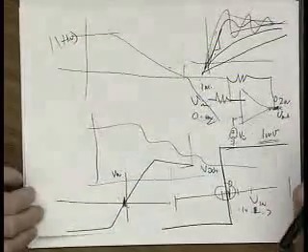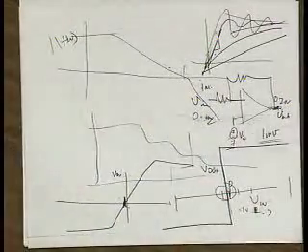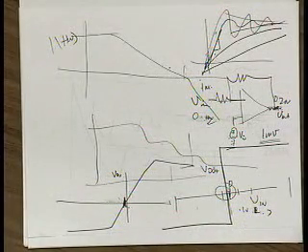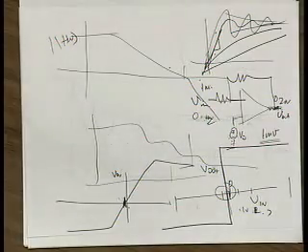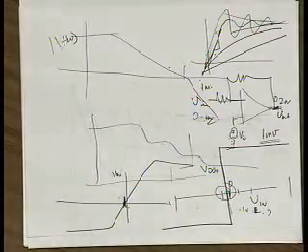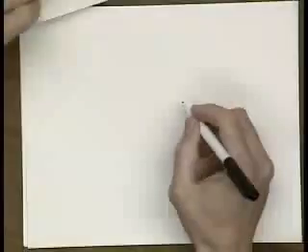Now the other question was process variation. So we've got a couple of different process files now, different SPICE files. How do you attack this? When you do DC biasing, do as much as you can to have things ratioed.